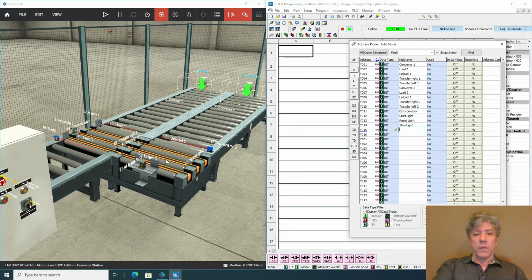In any transfer here, I will never want to take a pallet from conveyor 1 and move it over to conveyor 2, so I'll never transfer to the right. A pallet on conveyor 1 needs to be merged with the pallet stream from conveyor 2 and put onto this exit conveyor. By the way, the exit conveyor, you can only see a bit of it. The output on Y11 is the motor for the exit conveyor, and you can see it just to the right of the control box.